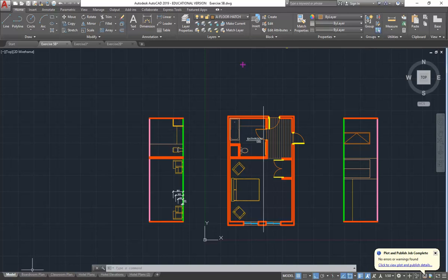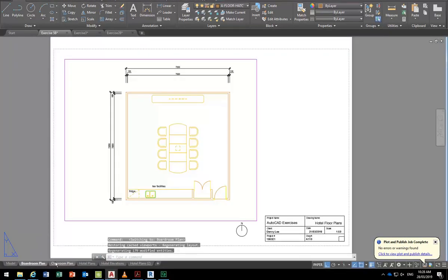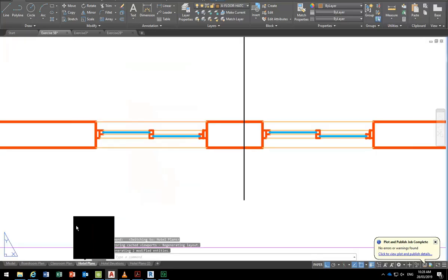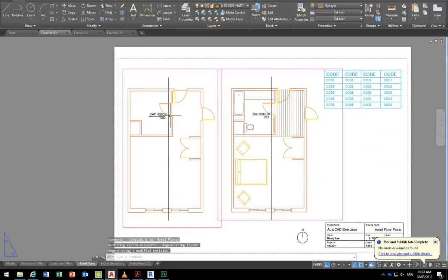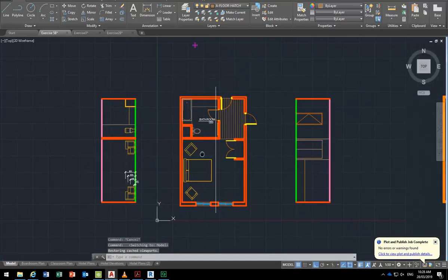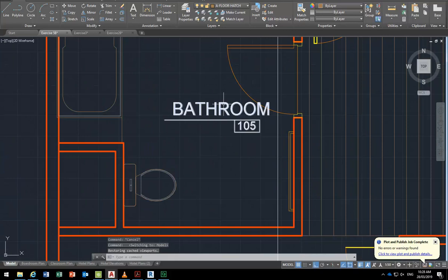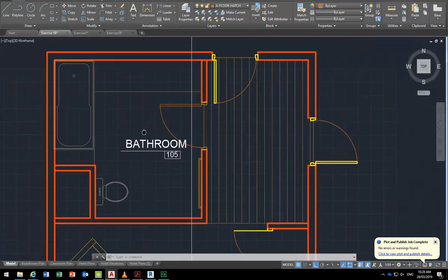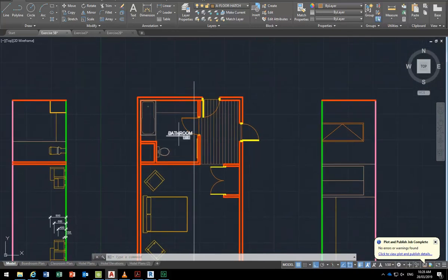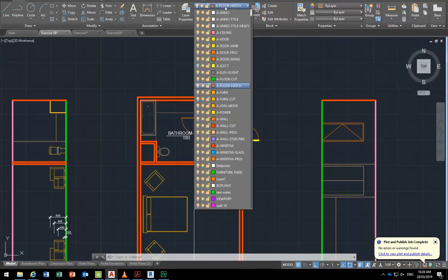Okay, so I've just come back to the Model tab, having set up these layouts, because now I want to add things like the section references and the drawing references and all those symbols that you'll have in the blocks folder that we want for the annotation. And I've already added some, so I've got this room label that's already been added. And notice that it's white because I've put it onto the layer that I've made for annotations. I've called it A-Anno.